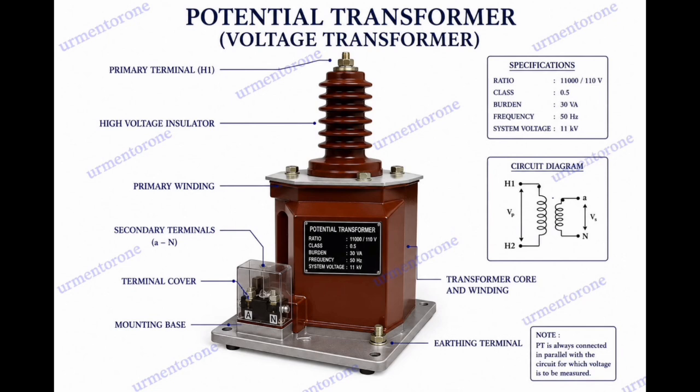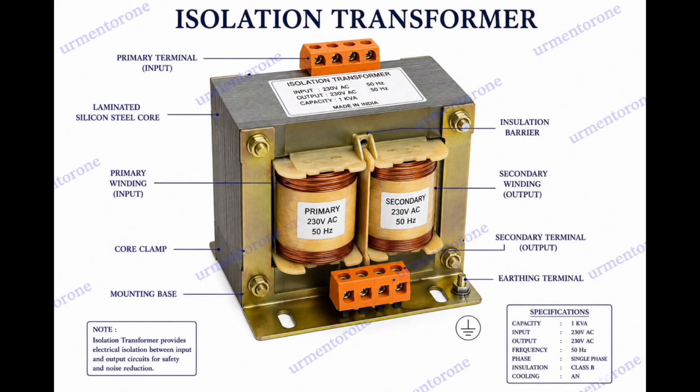Fourth one, potential transformer or voltage transformer. Potential transformers are used to step down high voltages to a safe standard level, typically 110 volts, for wattmeters and protective equipment.